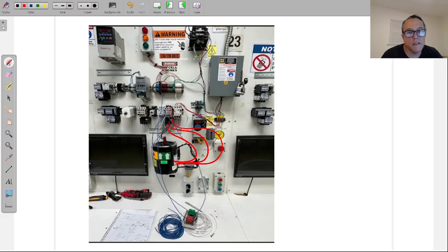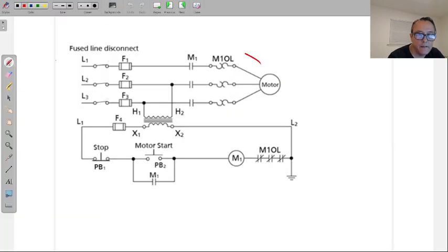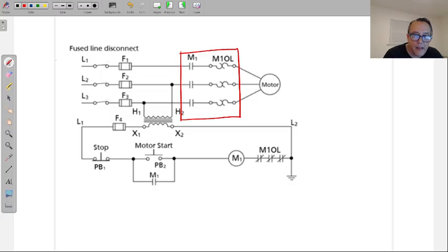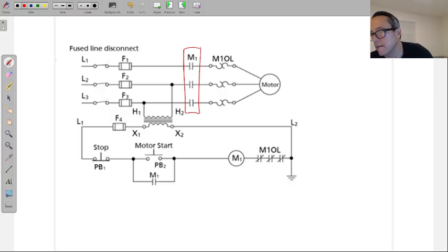The motor starter itself is not the control device. If you'll remember from our wiring diagram, it lives on the power side. These are the symbols. They don't really put a little square around it the way I am doing it, but that is our motor starter, made up of two components. The contacts, which I actually have here. I have the contactor part here. This is the DC one, but the contacts are inside of this. You can hear them rattling in there.